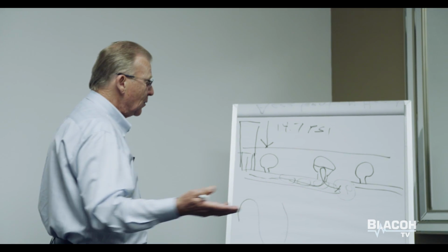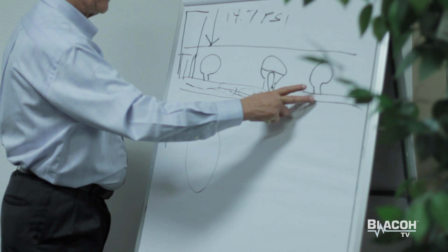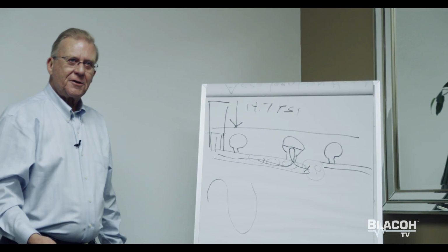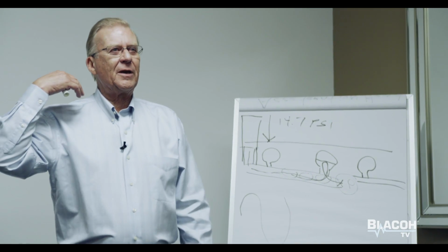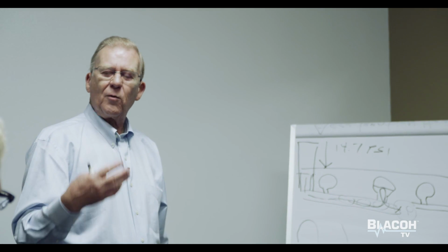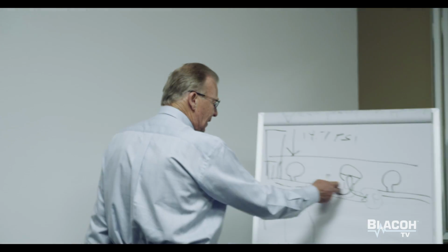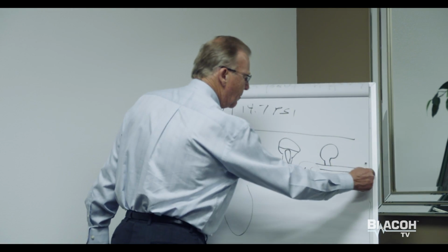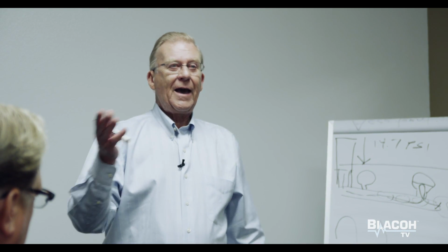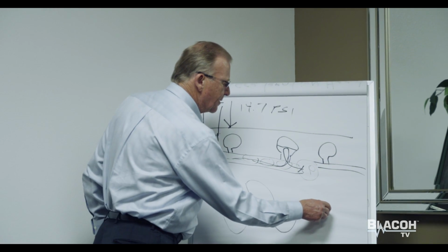In effect, with the inlet stabilizer or the pulsation dampener located within these 10 pipe diameters, okay, we have eliminated acceleration head. You're not going to totally eliminate all of it, but we have eliminated the majority of it to the point where it no longer has to be a consideration, okay, on the inlet side and everything past the dampener on the discharge side. We have in effect turned this into this.